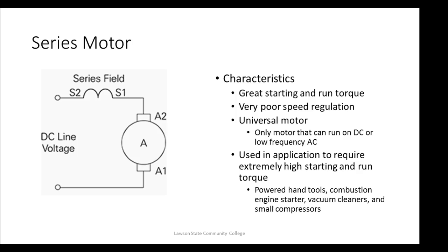Now what happens is that if you got power on this motor and you take the load off of it, it will run away on you. Now what happens when it runs away? So you got all these windings in the center, and when something spins, what happens to those windings? They try to do what? They tear apart, and these guys will literally sling themselves apart if you run them unloaded.